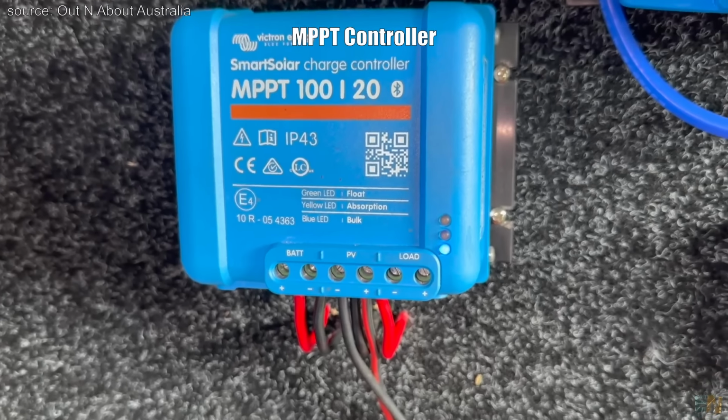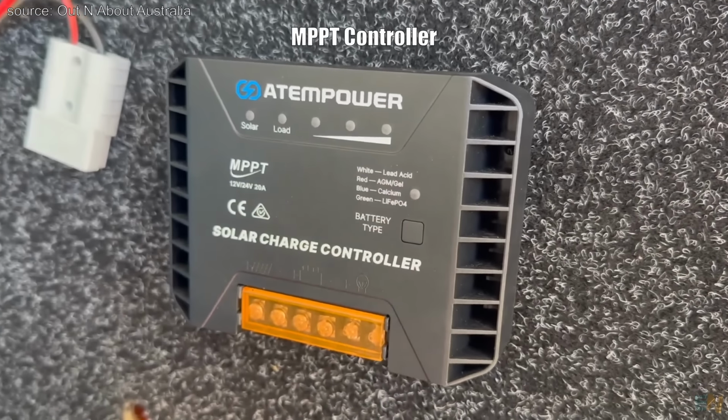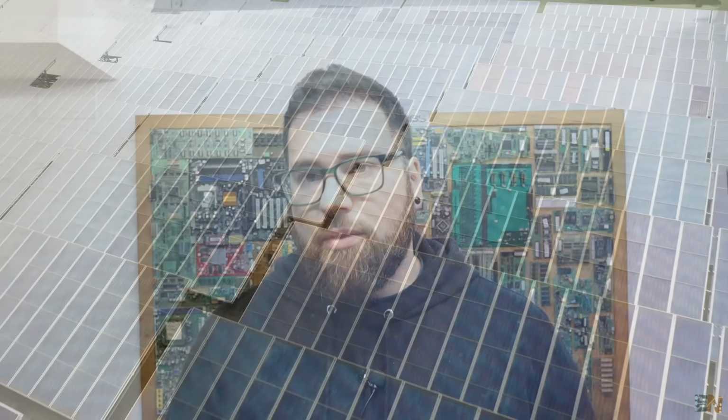So that's why we need this controller that can decide what voltage and what current we need at any time, so the power that we are getting out of the panel will always be the maximum power. So that's what a variable power source would be: a solar panel, wind turbine, and so on.